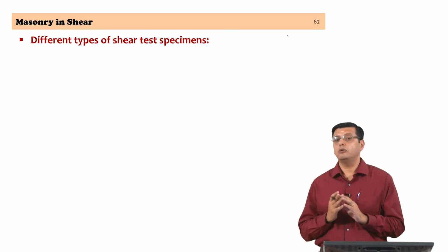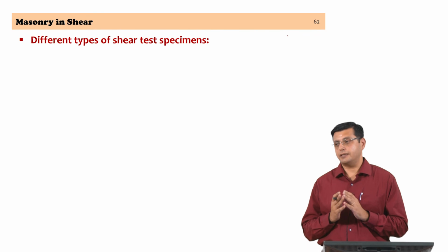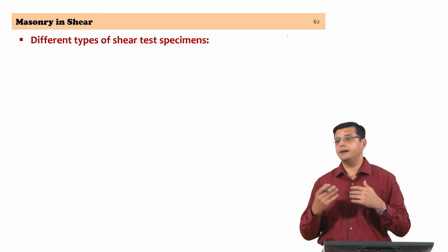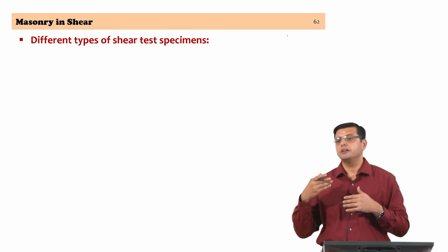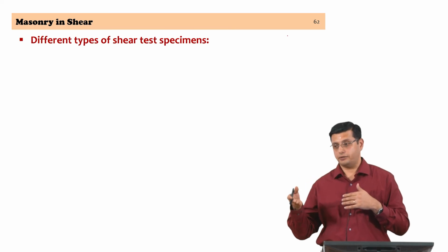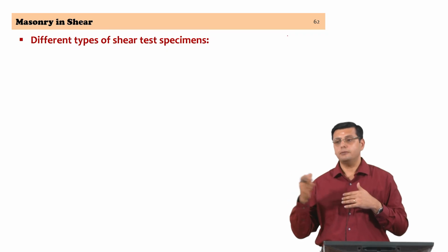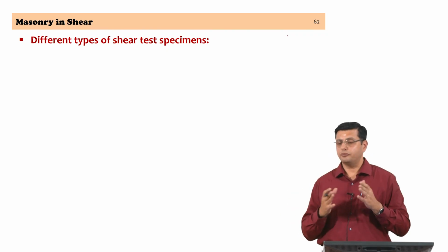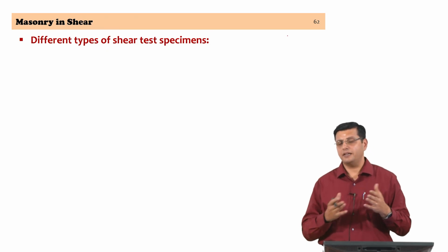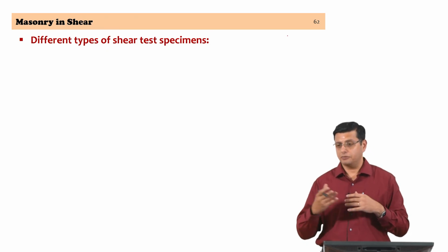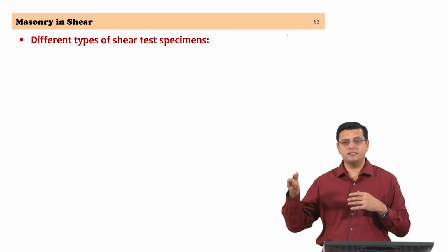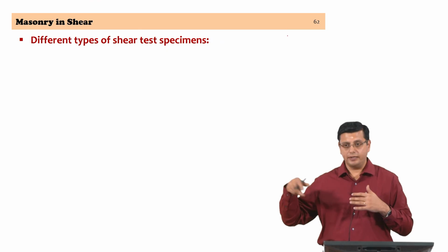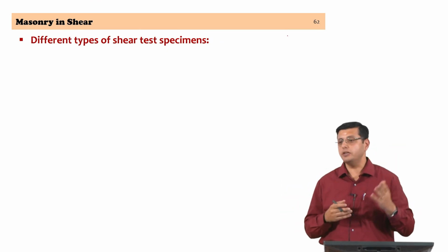Okay. Now, the reason why that matters is you might have a situation where the failure may not necessarily happen in shear in the joint, it can actually rip through the masonry units. So, the type of shear failure here is classified as line failure and a stepped failure. Stepped failure is taking the profile of the joints, whereas the line failure just rips through the unit.